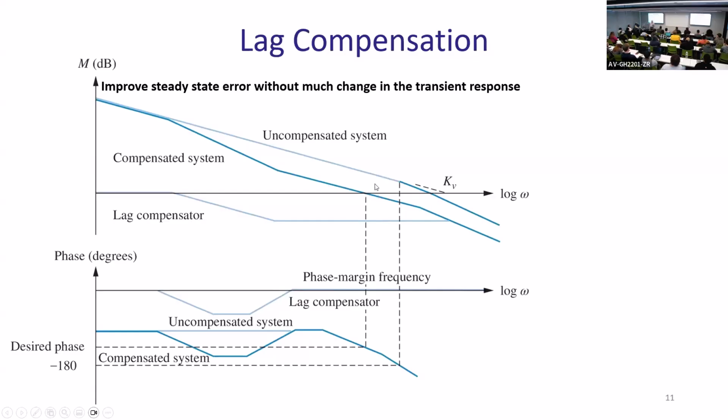So you're moving the phase margin to the left, where the phase is typically higher, because the phase looks like that. Typical system. So if you move your omega to that side, your distance to negative 180 from your Bode phase will be bigger. So this distance will grow. So this controller helps to grow that distance. This is the overall idea.